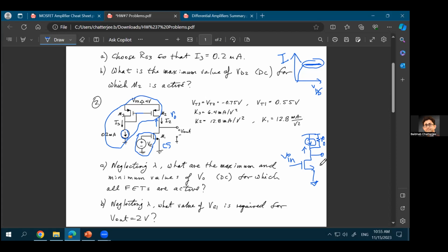So that's why all of these different concepts that we are talking about, they fall into place, because you can represent the resistance looking into the drain of this transistor as RO. You can represent that as a non-ideal resistance of the current source that you represent with this current mirror structure. And you can also represent it just with a resistance, with a value of RO. All of those approximations are correct. Again, as I said, you can approach the problem in multiple different ways, but all of them are correct.